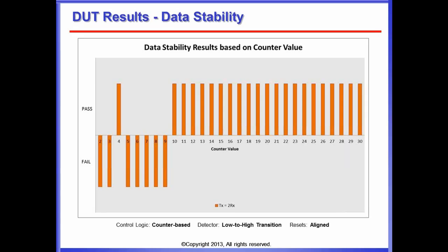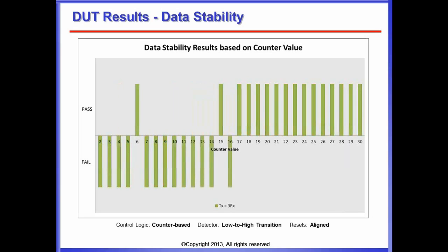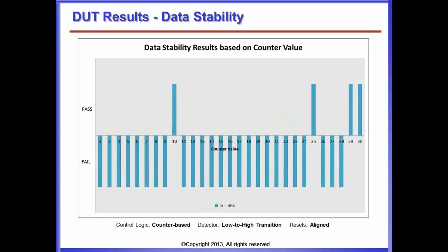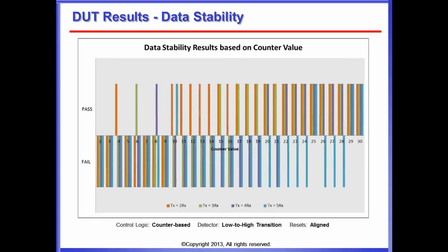So you might think that if you find out that 4 is sufficient and you change something in your ratio, or if you increase the counter because your clock ratios are changing, you can just assume that it works. In that case, it doesn't actually. So if you go up with the ratios, you see that this is not symmetric. This is not really linear, which counter values pass and which do not.